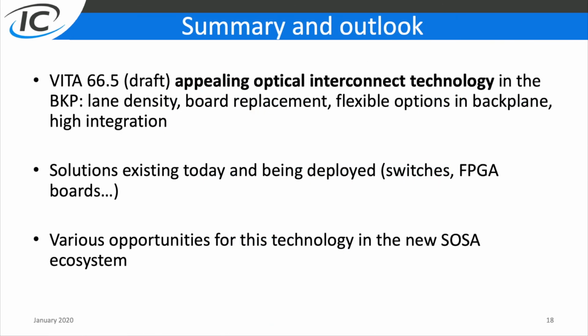So in conclusion, we talked about VITA 66.5, which is a new optical interconnect standard. The standard is in draft stage, but offers some promising benefits, such as the ability to increase the lane density on VPX backplanes, and the fact that it makes board replacement easier in the field, supporting two-level maintenance.